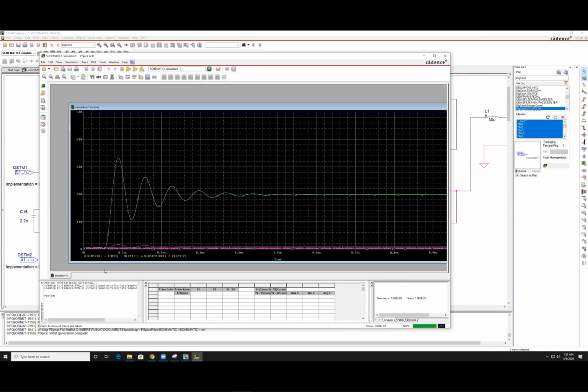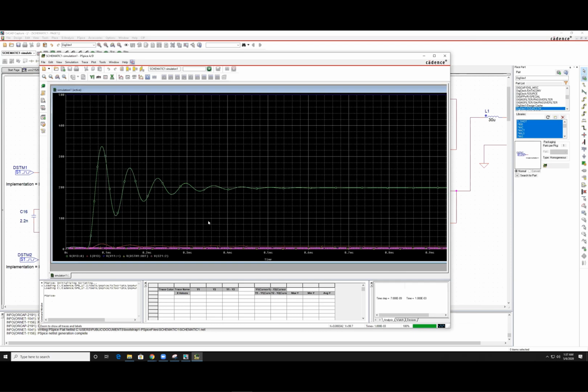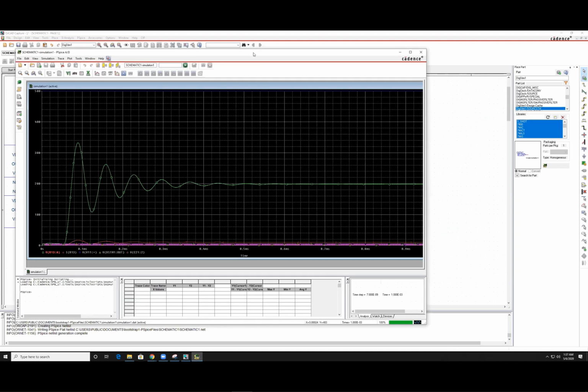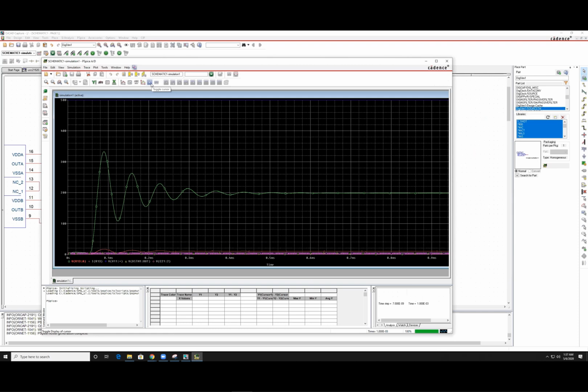And we're back, and this is the simulation waveform you should get. Let's look at the voltage. The reason why it says R13 is because that's the voltage at that resistor value, R13. And as you can see here, we can just hit the toggle cursor, click on the waveform you want to see. The plots actually come out nicely here. So at some time as it stabilizes and it goes into steady state, we find that the voltage is around 198 and our current output is almost at 10. So we got the circuit working to our parameters.